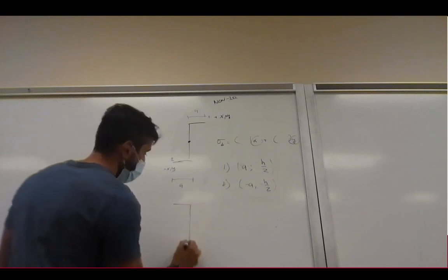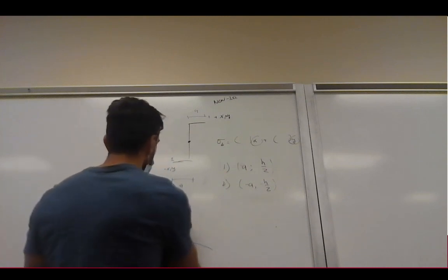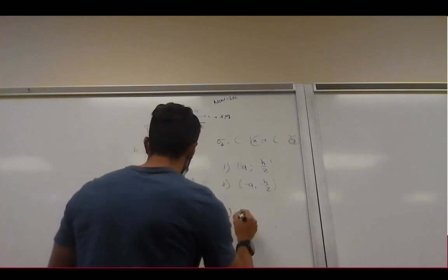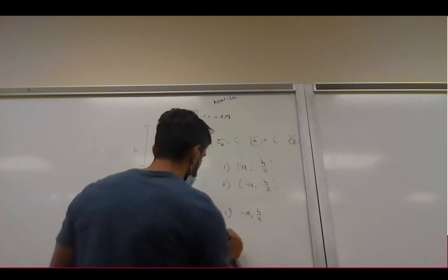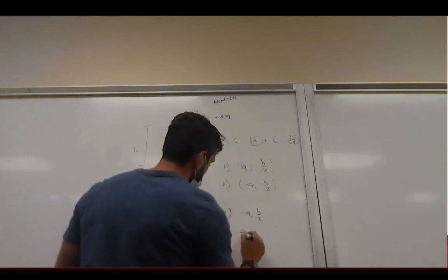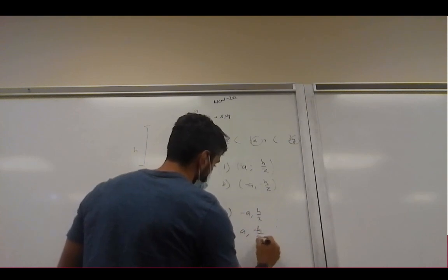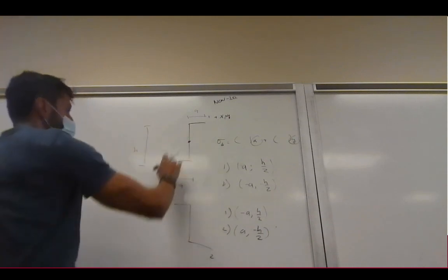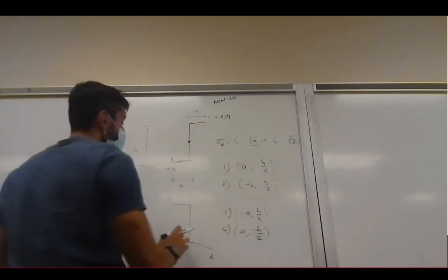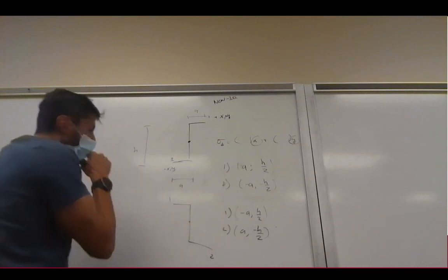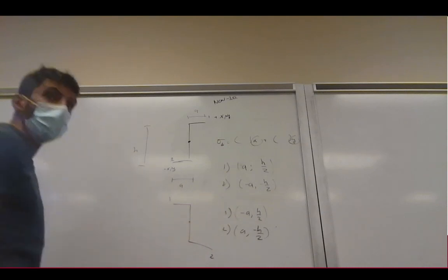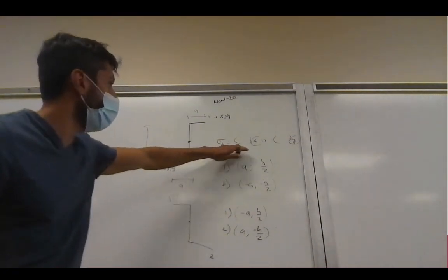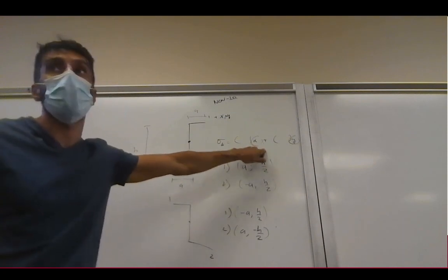And then if we look at point 1 and 2 from this cross section, 1 will be negative a, positive h over 2, and 2 will be a, negative h over 2. So that will be a coordinate system if you want to evaluate for this section the sigma z at point 2 and 1, and for this system, if you want to evaluate the direct stresses at point 2 and 1. So in these cases, x and y, which we see in the stress equation, are the coordinates of where you want to evaluate it with respect to the centroidal axis.